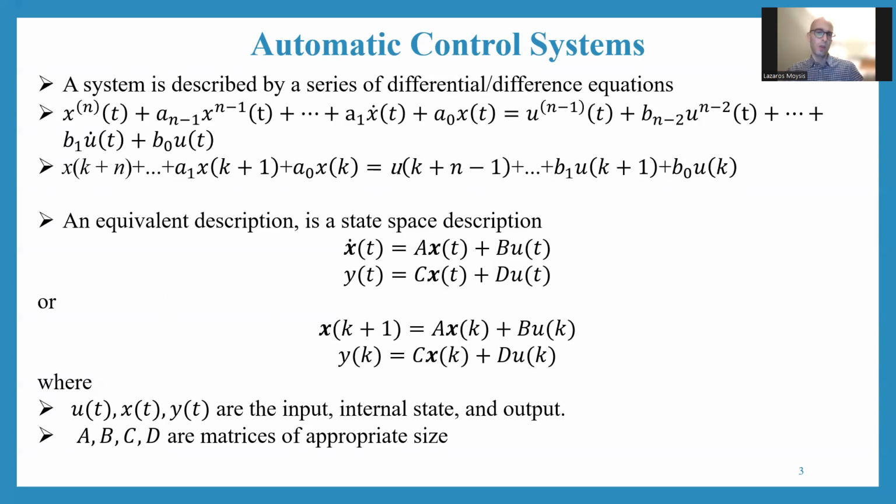So one might think, okay, Lazarus, what's the point here? Why isn't it better to have one differential equation of higher order than having far too many differential equations of first order? Upon first inspection, we may think that it's better to have one, even if it is a higher order. But in actuality, it's much better to have many differential equations of first order, right? Because in the linear case, what you can do, and that's what Kalman proposed, is that you can do amazing stuff in analyzing the system and in controlling the system, but using matrix theory.